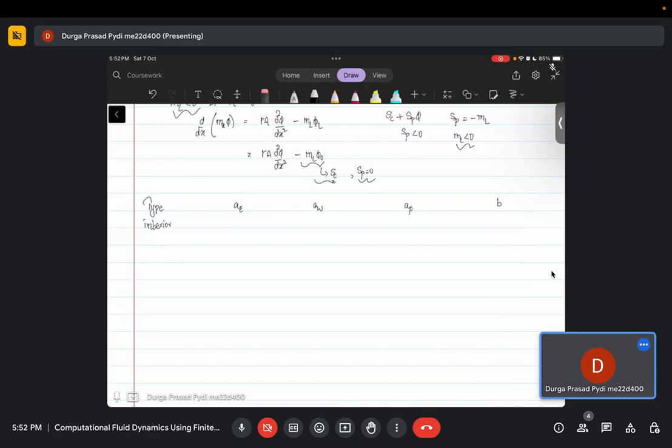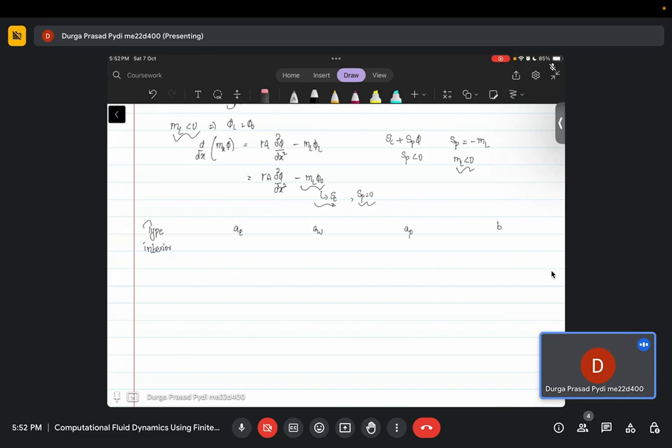Now you have to remember that in this case, when you discretize this equation, you will be getting an mx term, that is your flux. But since ml is negative, your flux will be what? Is it positive or negative? Maybe we should derive that first. So I have my equation as dmx by dx is minus ml. This gives me m equals m naught minus ml into x,